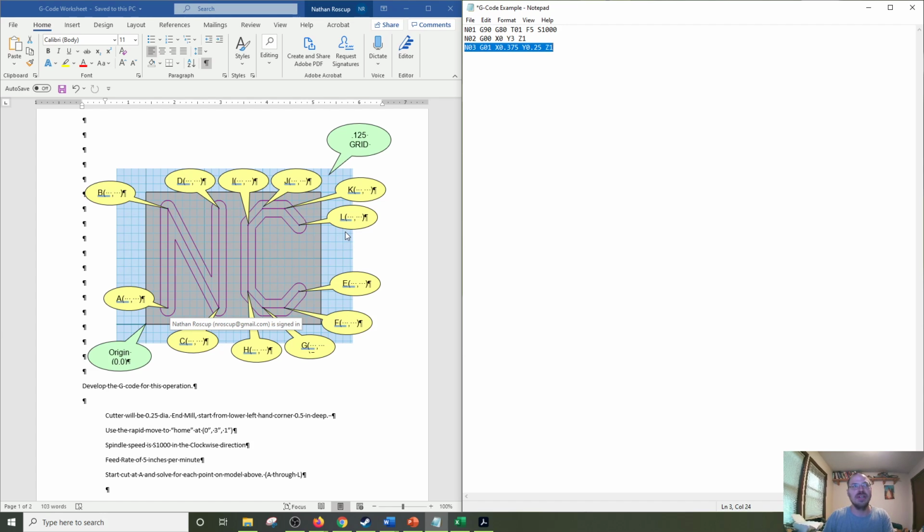This is typically where you're going to end up using a different kind of function, actually. You're not going to necessarily want to bury the tool right into the point where you want it. This is typically where you're going to change your feeds and speeds, and Mastercam is nice because it does that for you. You tell it how fast you are, how big of a cut you want to take out, and then it does all the rest.